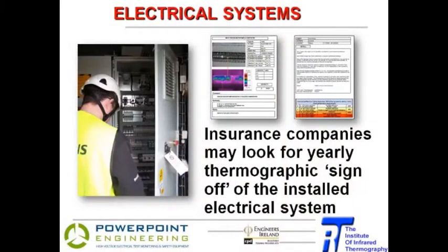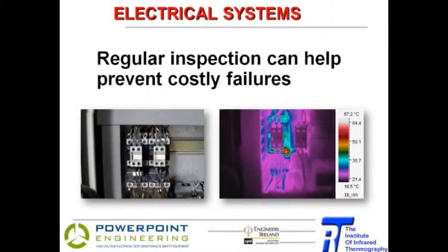It says there, may well be looking for yearly sign-off. What you're doing is you're producing a report where you look at every panel. And now you can demonstrate that on that day and at that time and under those conditions there were no problems. You may well find problems when you do a yearly sign-off inspection. It's not uncommon to find problems. Well, obviously then the insurance company might say you need to address that before the insurance cover is back in place. Could work against you. But again, very effective. Thermography is very quick and very effective. And regular inspections could prevent failures. We use thermography as part of predictive maintenance programs.